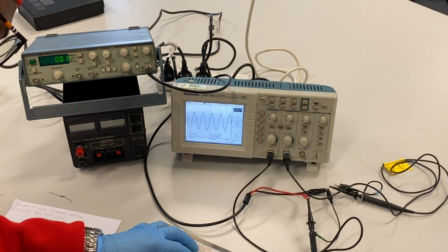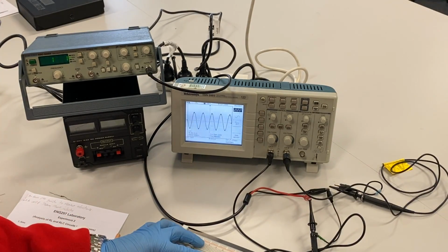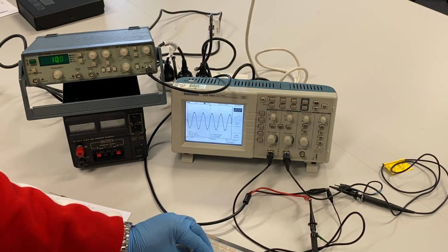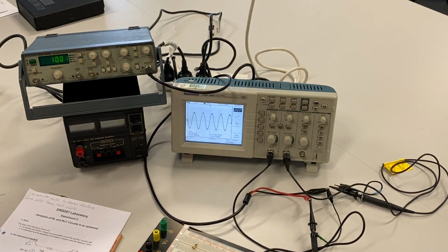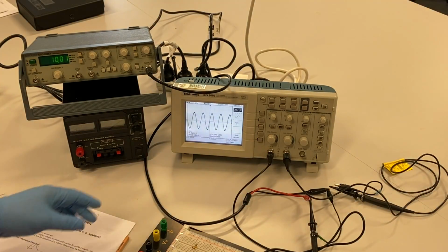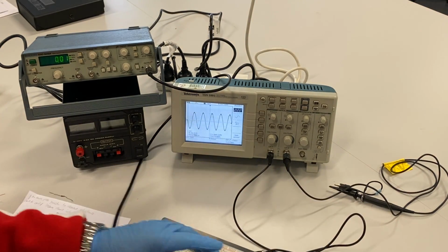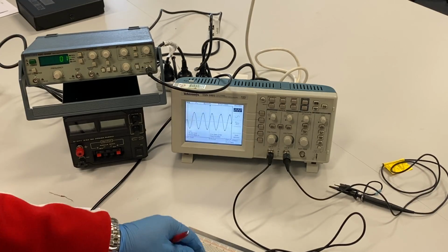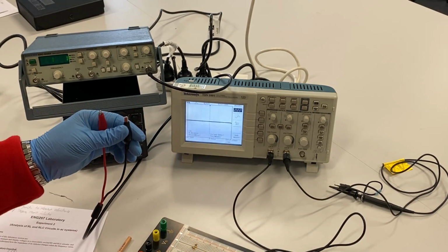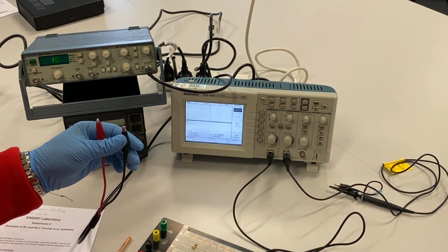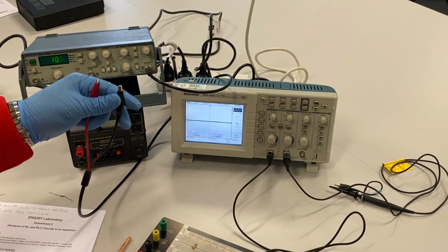I could, if I wanted, make this inductor jump this, but since the inductor is a little bit simple, I'll do this, right? I put my 1 kilo, 10 millihenry inductor. Then what do I do now? I connect my input voltage. This is my input voltage, and I'll connect channel 1 exactly where my input voltage is. In other words, channel 1 and input voltage are going to be exactly the same node, right?